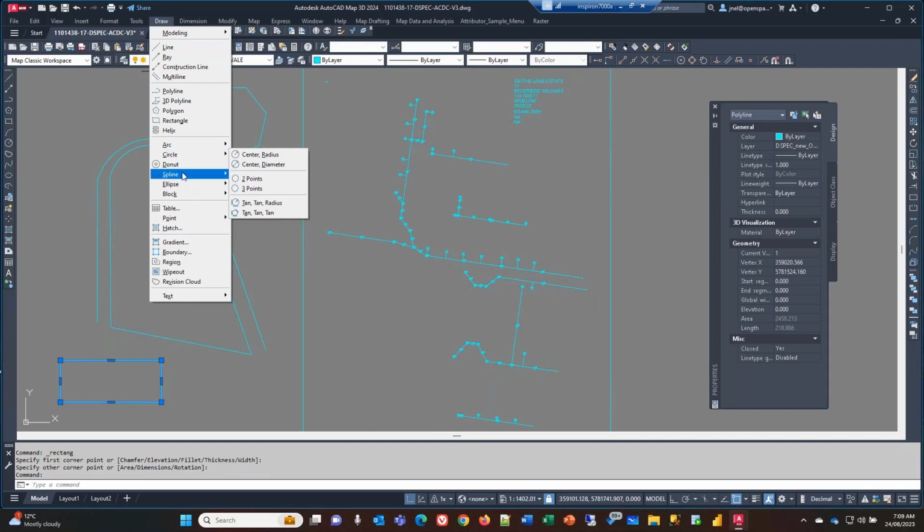Circle is a different entity that you're working with. And then you've got splines and ellipses. Now, coming from a GIS background and having to convert data and working in databases, I'd recommend staying away from splines and ellipses, because as mathematical constructs, different systems have different ways of handling them and how they inscribe, so you may not get the results you expect moving data from one side to another. It may look pretty on a map or on paper, but programmatically you may get unexpected results between different systems working on splines.